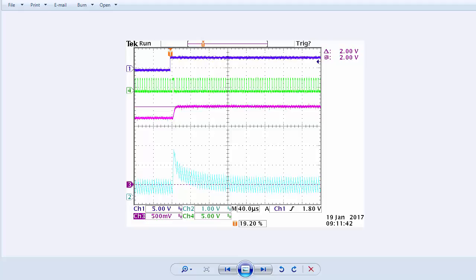Depending upon the speed of the processor and the sampling rate of the system, we may find ourselves short on time if there are too many computations to be made in each cycle. In this system, we are running a 90 MHz processor and a sample rate of 5 microseconds.